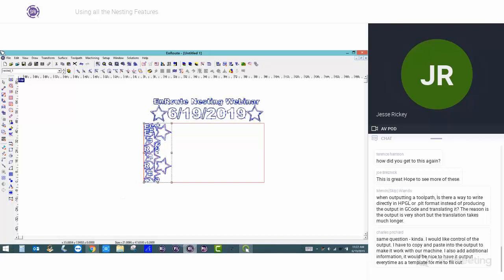Okay. Now let's go ahead and talk a little bit about a remnant. If I'm cutting out either hard to get material or expensive material, I may want to use what we call a remnant, or an oddball shape that's left over. If I'm just cutting out a rectangle or doing a material cutoff afterwards, probably not going to utilize this. However, like I said, if it's hard to get or expensive material, I may be able to squeeze one or two more parts in there, and if I can get more parts out of per sheet of material, it's going to be a little bit better cost savings.